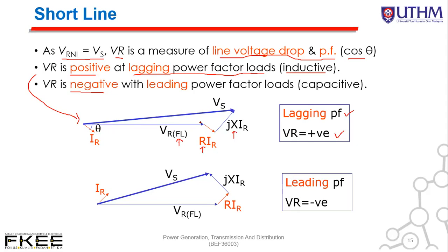From this we get Vs. We can see that the receiving voltage at full load is less than the supply voltage due to the inductive condition of the load. The current is lagging by theta degrees, so we call this lagging power factor with positive voltage regulation.